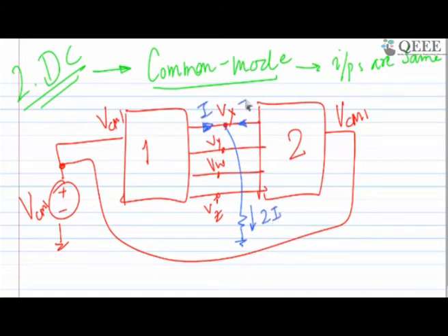This is what I can see. So in this case, this Vx potential is not going to be virtual ground. There is no virtual ground. It's virtual ground in only one case, when it's an AC signal you are applying with 180-degree phase shift. If you are applying the same voltage, it's still wrong. You will not get the virtual ground, and this is the place where people make mistakes.